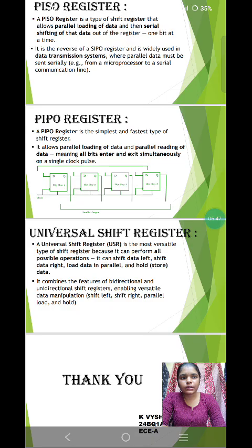Voltage drop. When current flows through a resistor, there is a voltage drop across it, also known as the IR drop. Power dissipation. Resistors dissipate electrical energy as heat. The amount of power a resistor can dissipate without damage is its power rating, which is related to its physical size. Types. Resistors can be fixed with a constant resistance value or variable where the resistance can be changed.